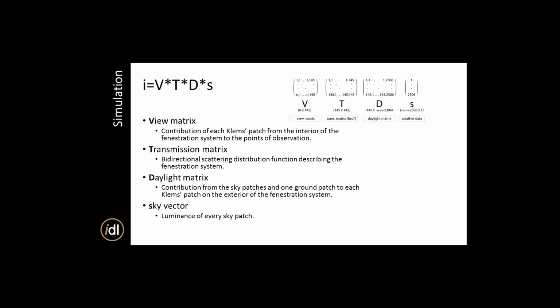So here's basically the breakdown. We're seeing matrices, essentially. We're turning a simulation model into coefficients that we can apply weather data to. Once we have these matrices, we can apply any number of weather files or EPW TMY3s as we want. So we're running one simulation and then doing math after that.